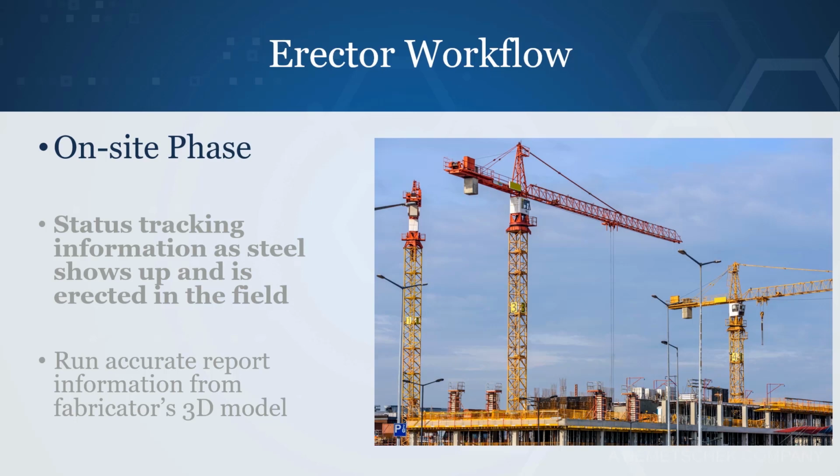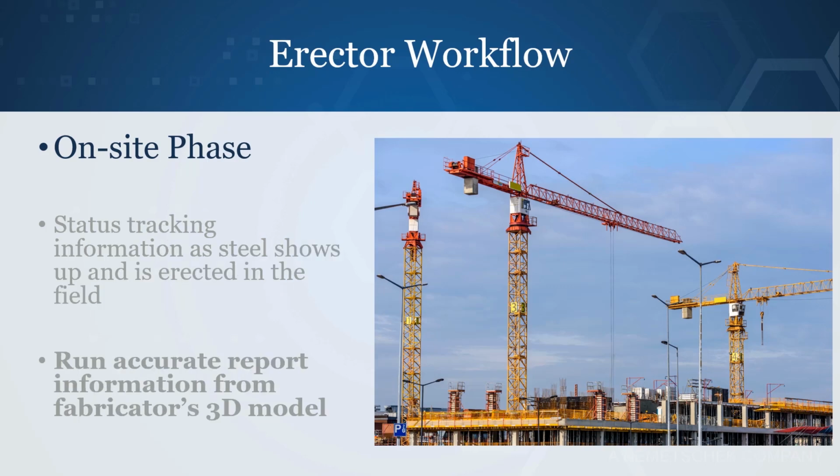Today I'm going to be covering once the steel actually gets to the site and how SDS2 can help the erectors. I'll be able to track the productivity of the steel erected, and it's going to show up on site, and then it'll also show up in my fabrication model, and maybe even in the shop. Then I'm able to run accurate information from that 3D model since it's going to be the most accurate, and that's going to help me see maybe how many field bolts I need, maybe even a summary, maybe my field bolt point-to-point list, and I'll go into that more in depth later on. If you have any questions throughout the webinar, feel free to type them in the chat area and I'll make sure to answer some of them at the end.